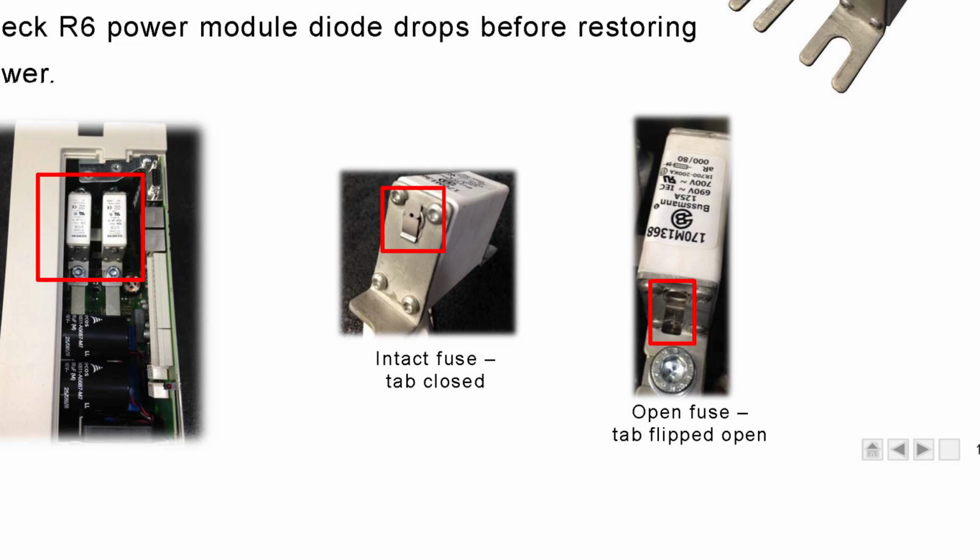That indicates the fuse is open. So when they blow, sometimes they blow one at a time. I've seen both. If you have this situation, I know David said that you're probably going to send it back to KEB to have us take a look at regardless. That is fine. If you have this situation though, and you want to just replace the fuses, see if that's all it was, you can do that, that's fine. Just order the fuses, we'll send them out to you.